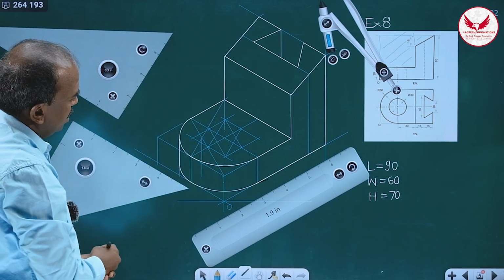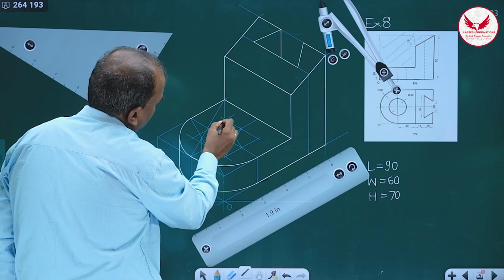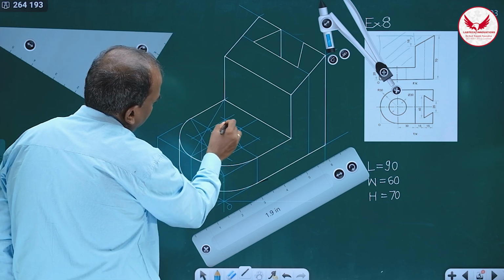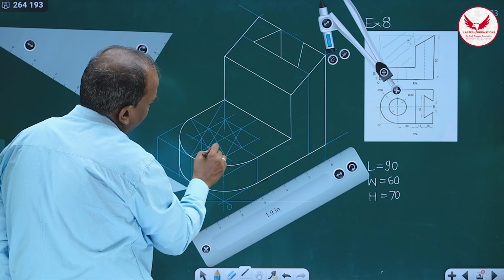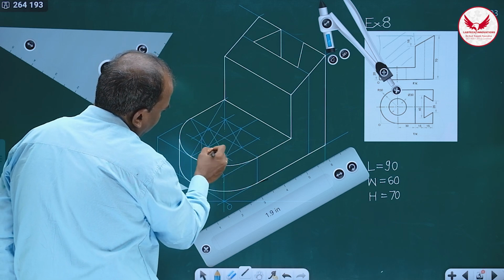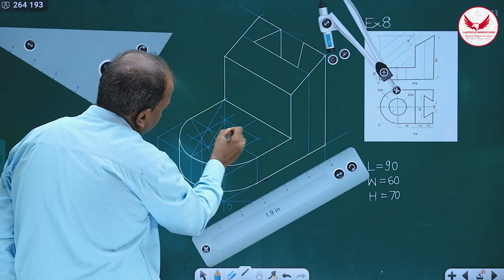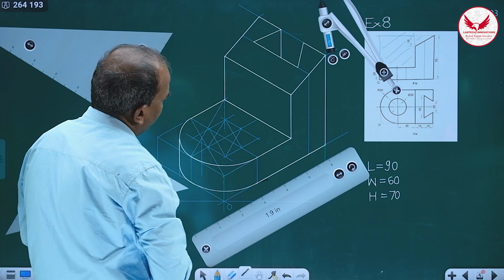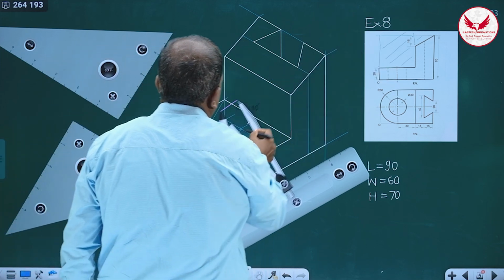Like this. Always, whatever two centers of the rhombus, meaning the 120-degree angle, these are going to be the two centers while drawing the ellipse, meaning the circle will be converted into an ellipse. From that, join the midpoints of the opposite sides, for this these two midpoints, and from this center these two midpoints. Now with the help of a compass we can easily draw the ellipse.